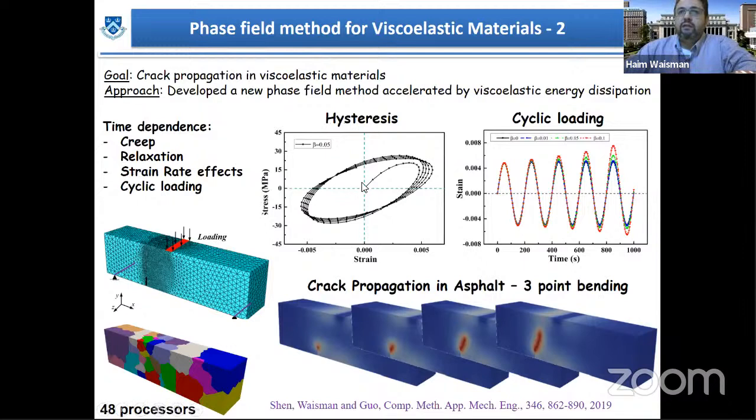And what you see here is basically an example where we have loaded a viscoelastic material. If there is no damage, then this circle will continue to basically coincide with the loading. And the energy described here is hysteresis essentially. But since we are cycling the system with increased amplitude, then damage is created, and essentially this ellipse, you can find it in this paper, will shrink and rotate at the same time due to this effect.